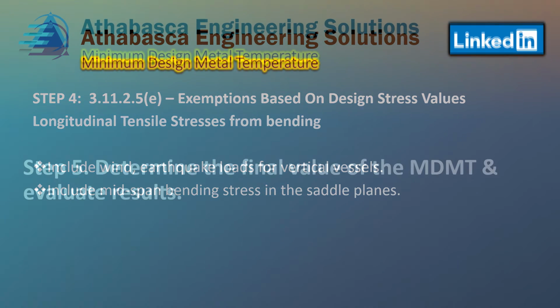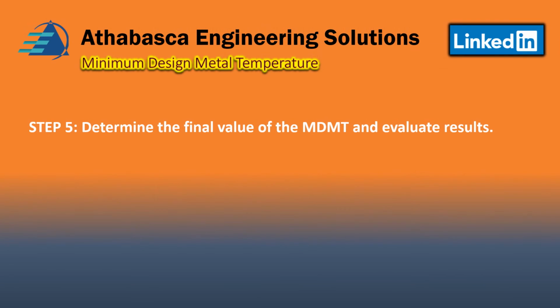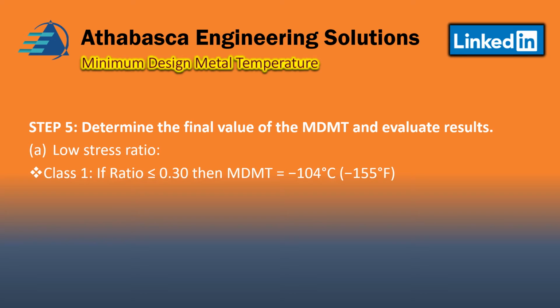So let's look now at step 5, determine the final value of the MDMT and evaluate the results. Let's look at the low stress ratio. For class 1 design, there's two classes of materials or designs, and the safety factor or design factor for class 1 is higher than class 2.